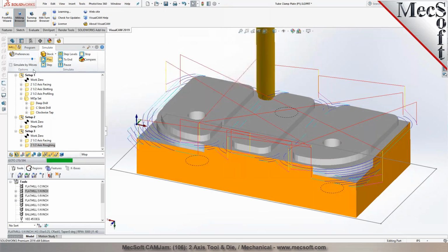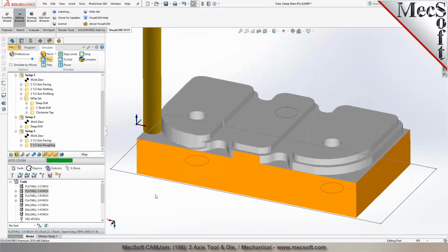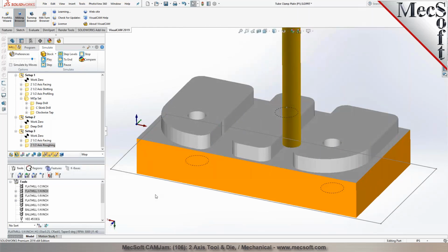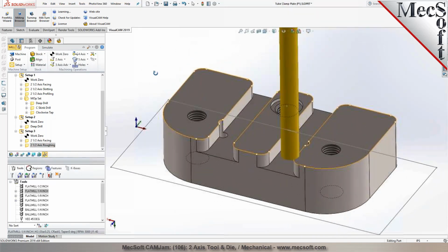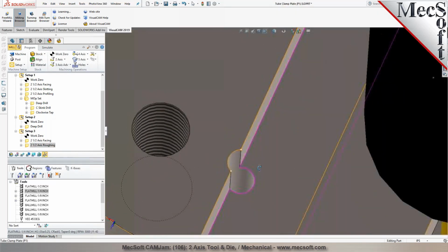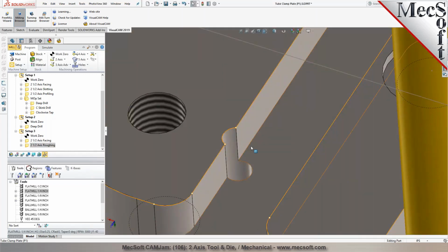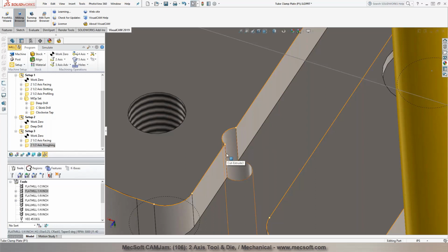Okay. Now, with the through holes that are on the inside of those two through slots, does that tool path actually cut in and follow that profile, even though that was put on in our other setup operation? Yeah, it will. The tool path will try to follow around this contour in here, right here. So unless you suppress this feature, but if the tool is too big, you'll see that the cutter cannot get in there. So it's not going to gouge the part or violate the geometry, but the cutter will try to get in if it's able to.